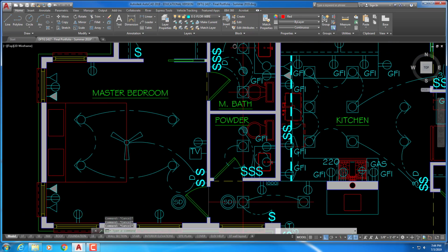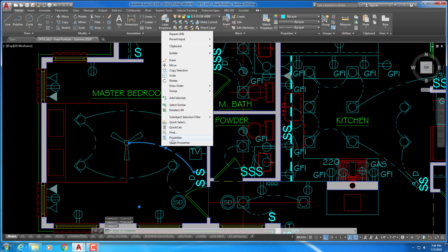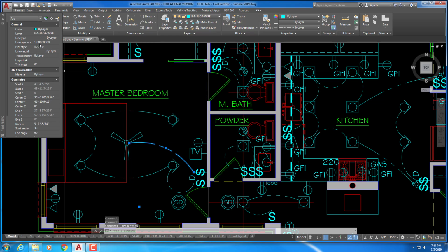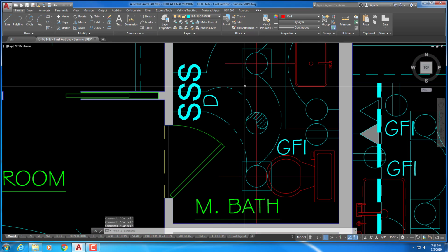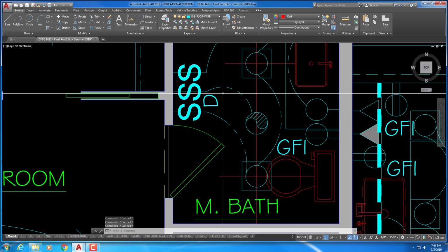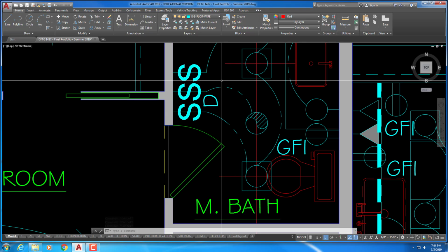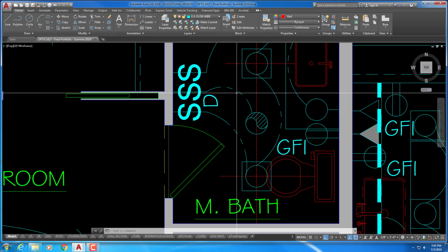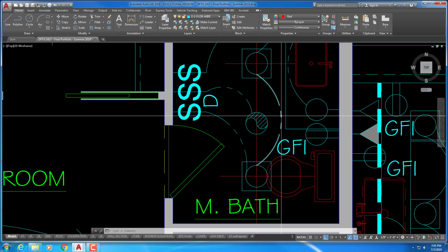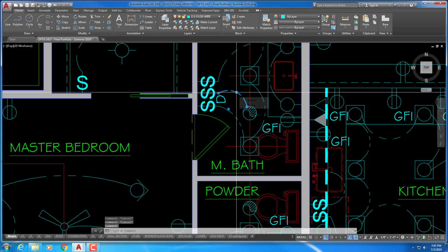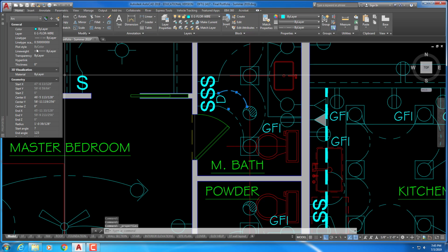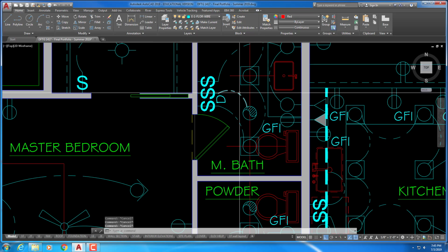Alright, so typically you want to use that 1.0 for the line type scale. There are cases where I do make an exception, and especially in cases like this, it's next to impossible to get that 1.0 to work in there. So anytime you see the smaller dashes, you can change it to 0.5, but your default should always be 1.0. Only change it to the 0.5 when I have. So basically you would just go into the properties and change the line type scale to 0.5 here. Because if you leave it at 1, it's not likely you're going to be able to get that in.